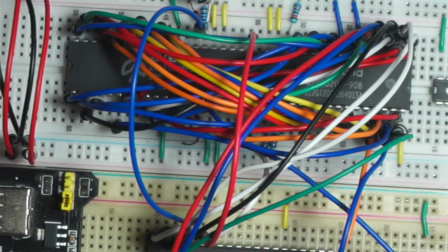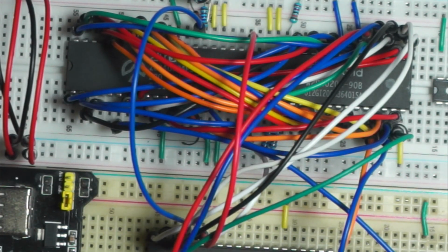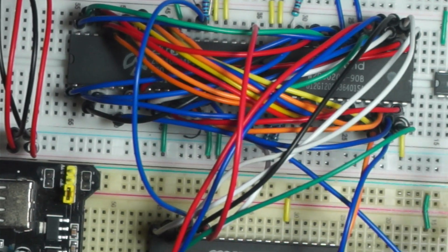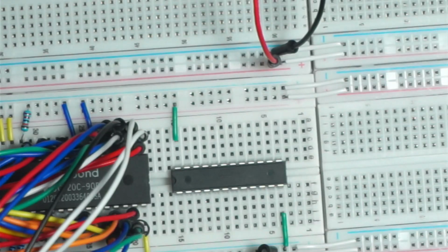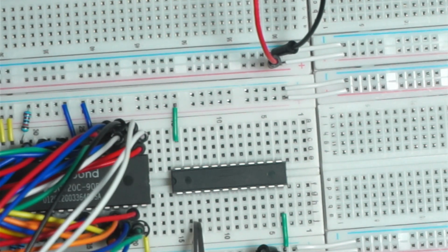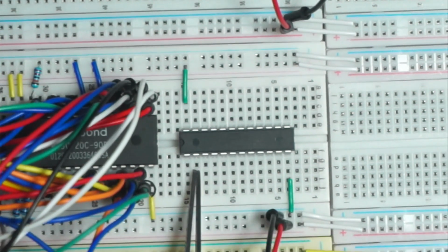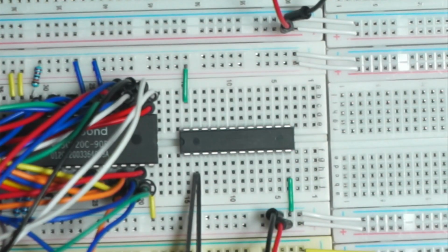Now I will wire the chip enable and the essential signals from the CPLD. But before I do that, I will wire the CPLD up. So I will look at the pinout that I have defined. So this pin 2 on the CPLD is the memory request from the CPU.